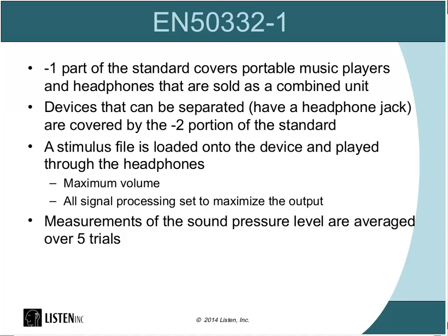So we play back that stimulus signal from the device through the headphones and then measure the output of the headphones through the ear simulators. We do this over 5 trials.